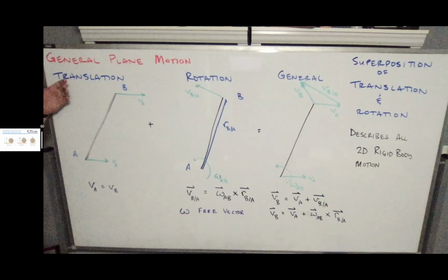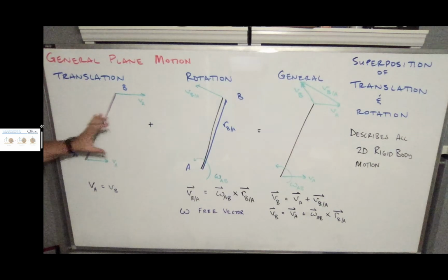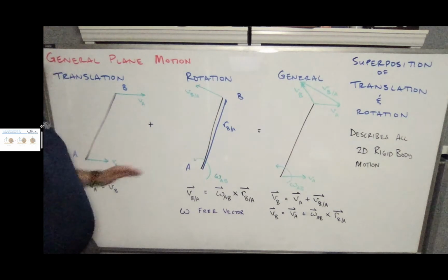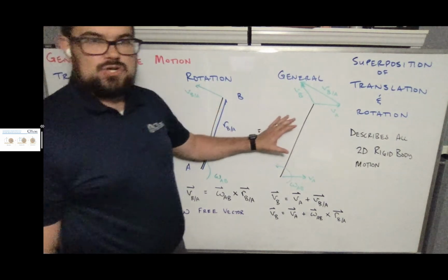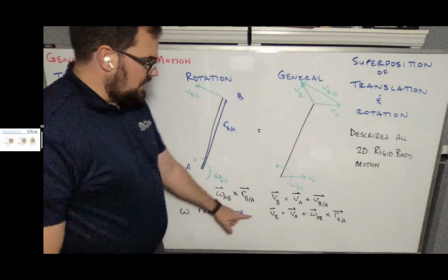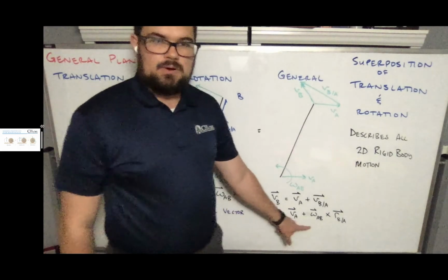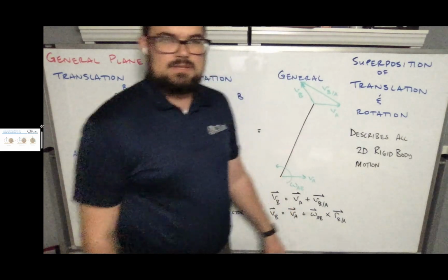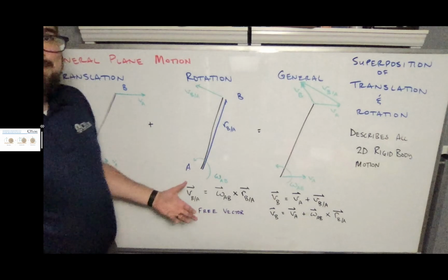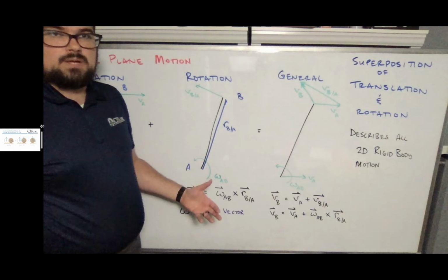We're going to use this in acceleration as well. That's in 2 lectures. But the idea is that we can map out our kinematic property diagrams for translation and rotation, add up the points at A, the points at B, and get our general motion. We can use our relative motion equation that combines both our translation component and our rotation equations, and now we can map any 2 points relative to one another.